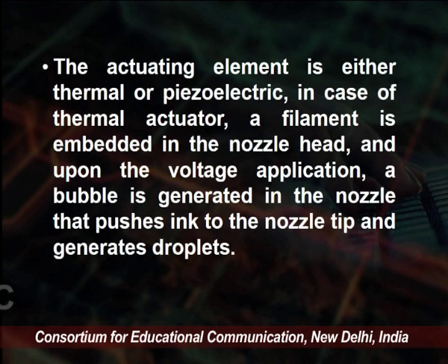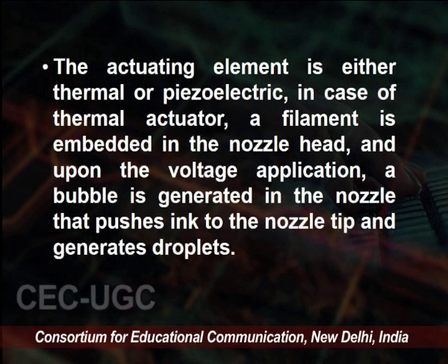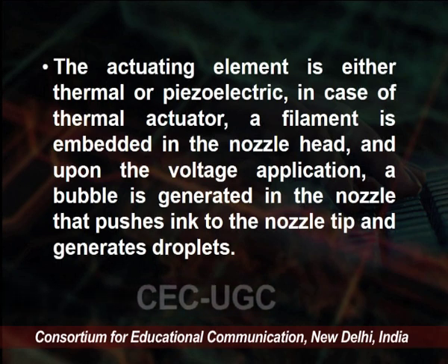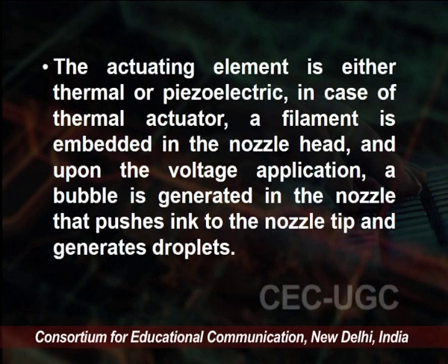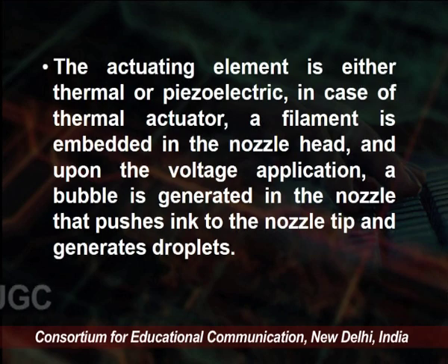Now, the actuating element is either thermal or piezoelectric. In case of the thermal actuators, a filament is embedded in the nozzle head, and upon the voltage application, a bubble is generated in the nozzle that pushes ink to the nozzle tip and generates the droplet.